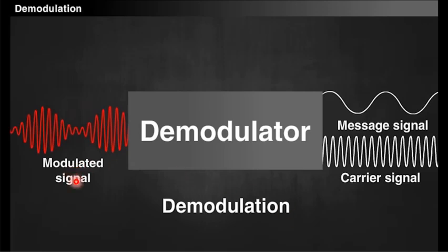So, the modulated signal is given to a demodulator in the receiver, and the demodulator will separate the low frequency signal, that is the information signal, from the high frequency signal, and it is given to an amplifier, after which we will receive a good quality reception at the receiver side.